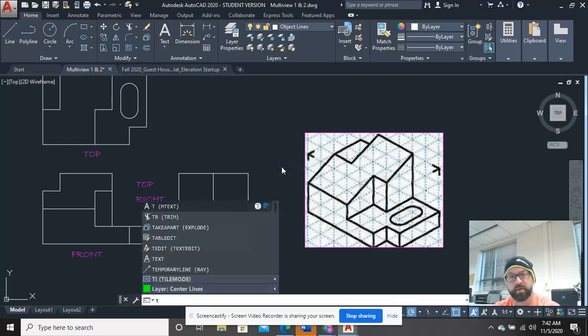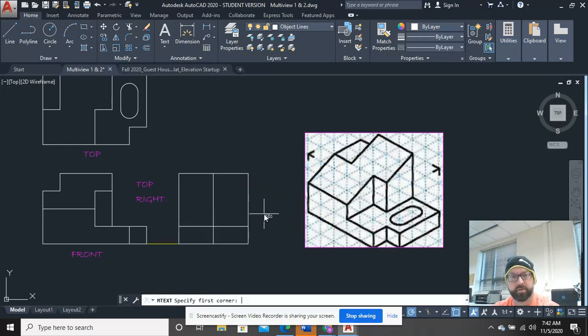But this line does not go through here, okay? TR space. Nope, not MText, TR space. This line does not go through the shelf, all right? And you're like, wait, this is all wrong because this is supposed to be a slope. Okay, so let's do this. I can either offset this up 1, right? Or I could just use my construction line trick, right? And I could draw a line right on top of this from this point up a height of 1. And now connect the dots.